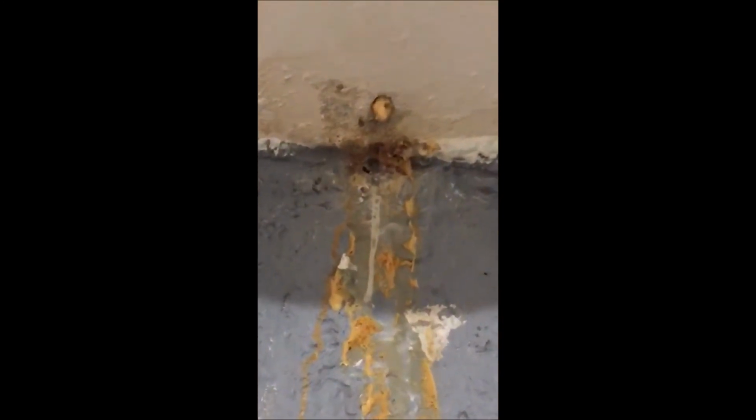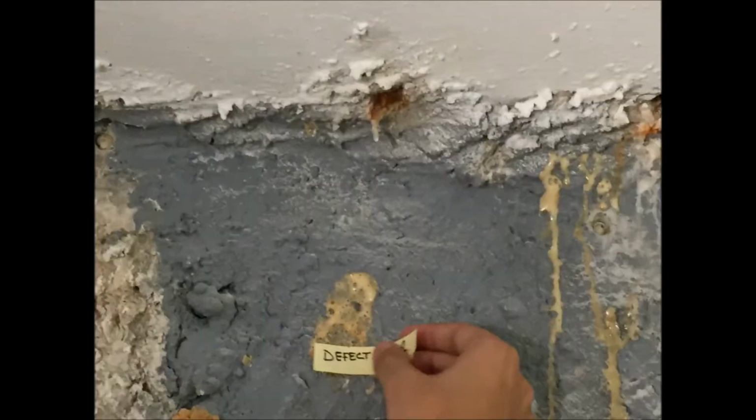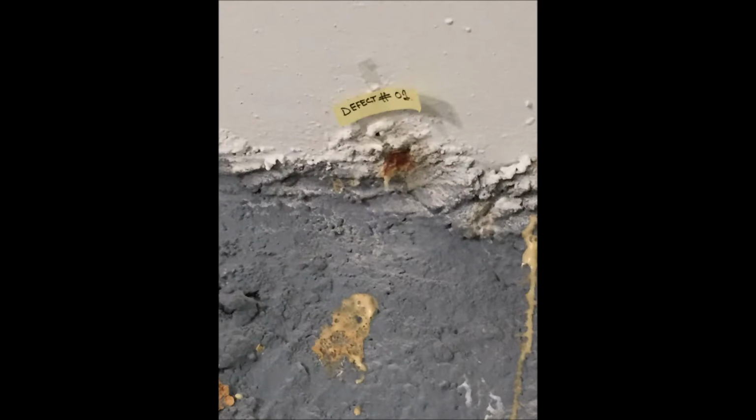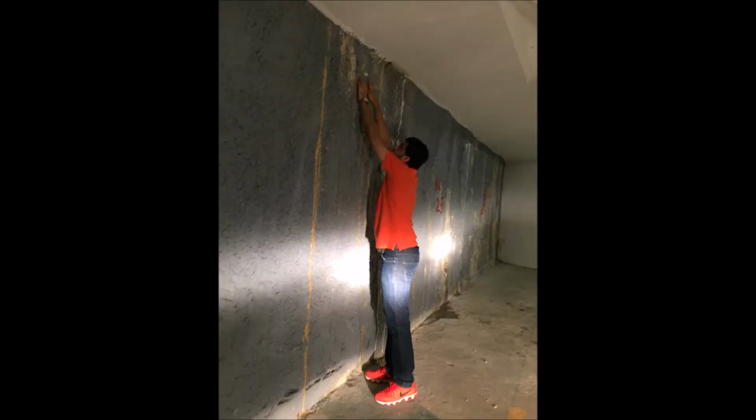After completion of plaster work and when it becomes completely dry, the soluble salts dissolved by moisture are drawn to the surface through pores. These soluble salts absorb moisture from atmosphere and on drying, they get deposited in the patches in form of white crystalline substance. The surface gets disfigured by ugly damp patches of efflorescence. This defect gradually disintegrates the structure. It is normally temporary in nature as it disappears during the wet weather and reappears during the dry.